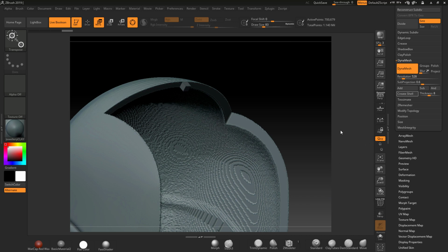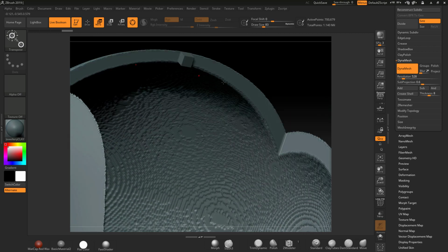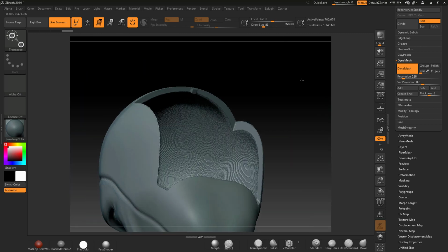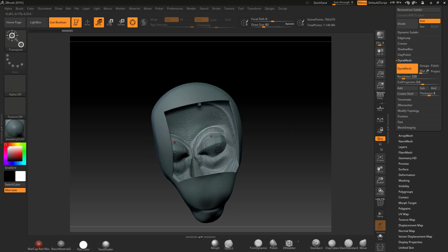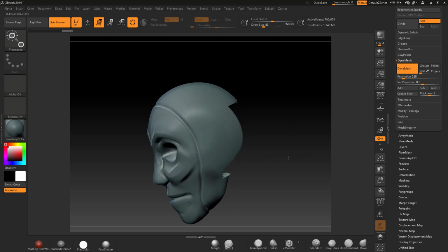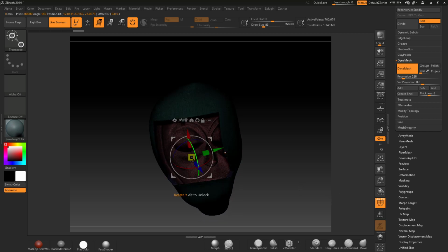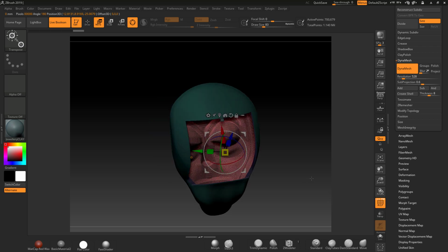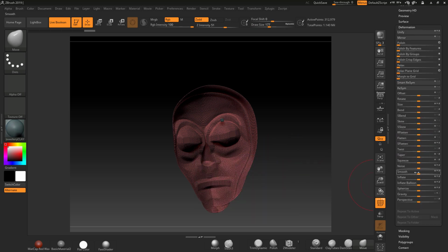Okay, so that's finished now, and if we look at this, you can see that this is now at 8, but it's 2 millimeters. So we have created a good mesh. Now you're going to see on the inside it's a little bit kind of faceted, but you could go into this piece, and because it's a separate mesh, you can come into here. Let me just turn line off, go back into draw. I could just select this inside and use something like the deformation smooth to kind of smooth it out.